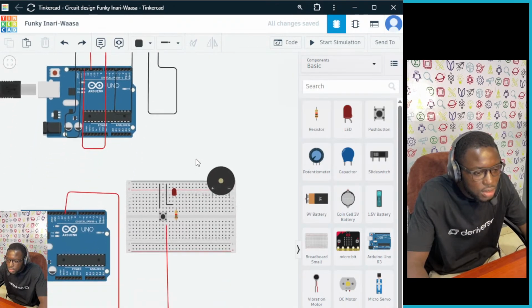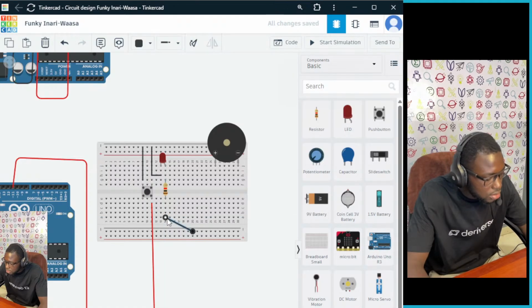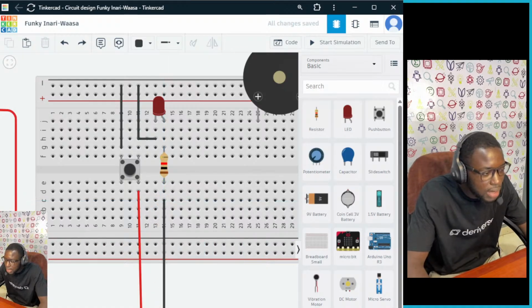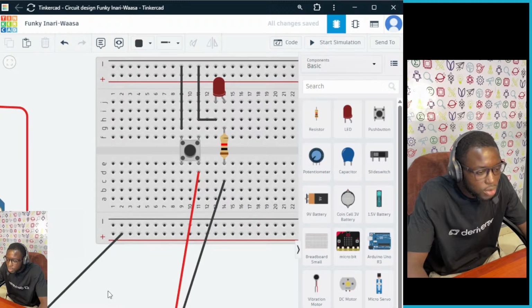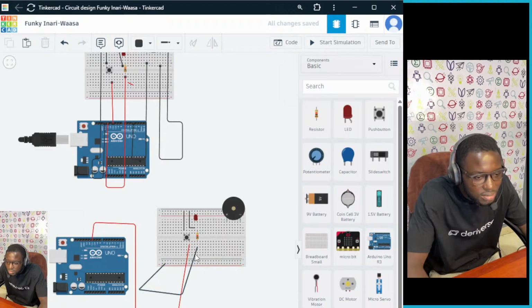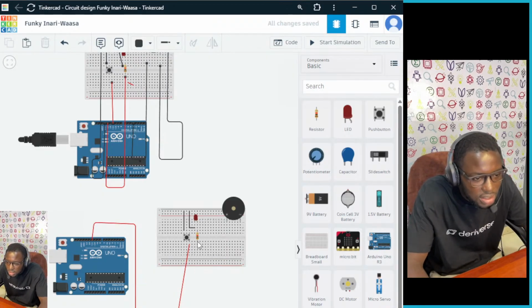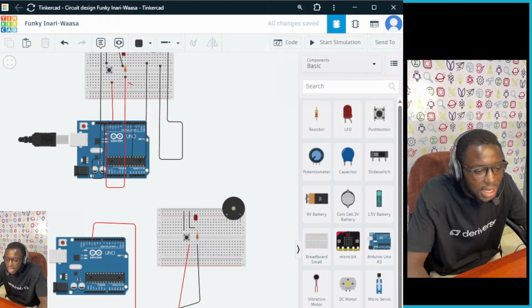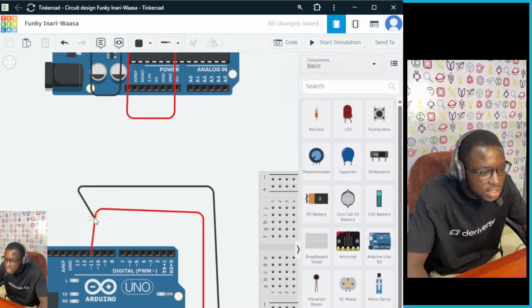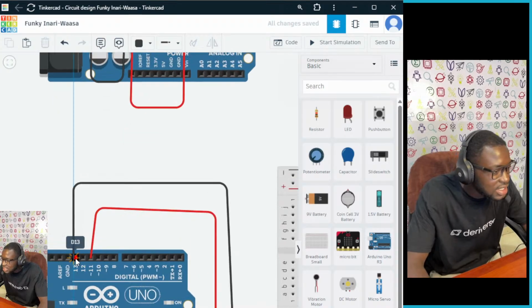So all I have to do is first make my connections. I'm going to click on this, move down, click, and still negotiate my curve, and make sure it is connected to my pin number 13. So right away, let me close this and make it again. I drag it, negotiate my curve, click again, click for another curve, and then finally over there, click, and then I can now connect it to my pin number 13, just as you can see here.